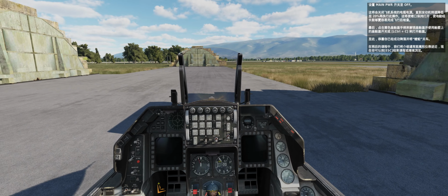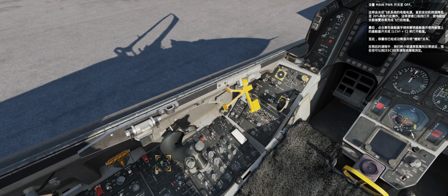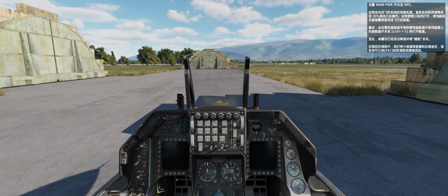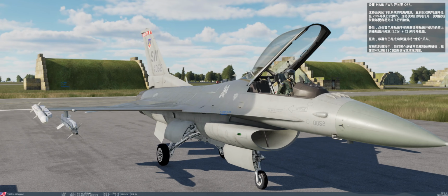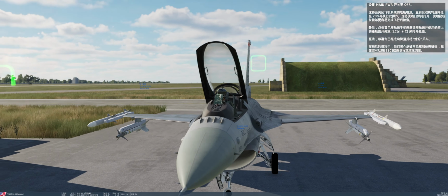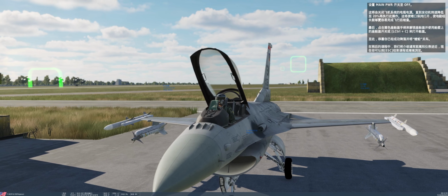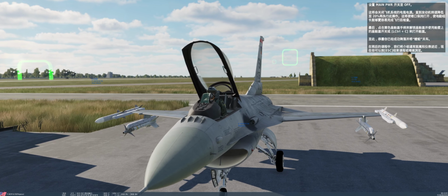Set the main power switch to off. This shuts off battery power to the aircraft systems. Delay this until after RPM decreases through 20%. This delay should allow the exhaust nozzle to remain open and make it easier for the crew chief to accomplish the post-flight or through-flight inspection. Then last, unlock the canopy by clicking the yellow canopy handle and open the canopy using the switch on the sidewall or left control seat.